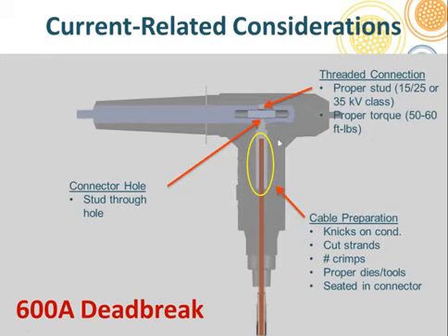And another interesting fact about this type of connection, if the elbow happened to move in the clockwise direction, that's in the direction of tightening the torque. So if you start with 10 foot-pounds, you would think, oh, well, I'm going to get tighter. What happens is it doesn't get tighter, first of all, and then when the elbow goes back to the neutral position, it moves in a counterclockwise direction. That will loosen up the stud also. So an area of concern. If the requirement is 50 to 60 foot-pounds, make sure you've got 50 to 60 foot-pounds.